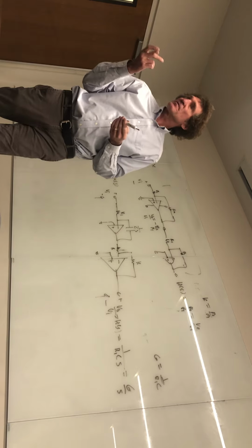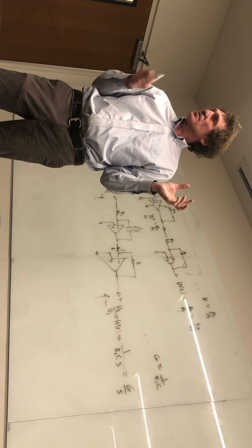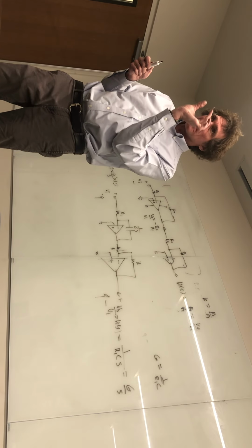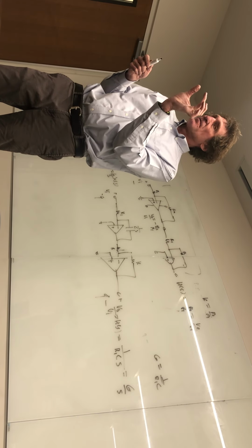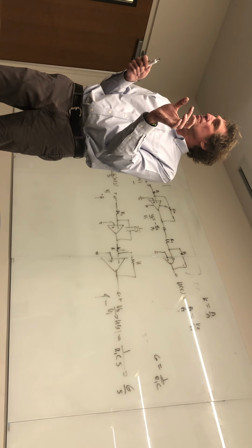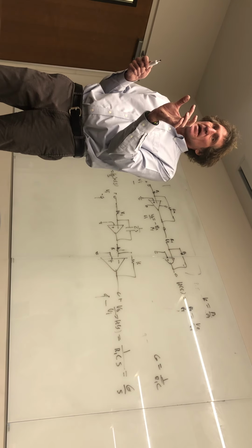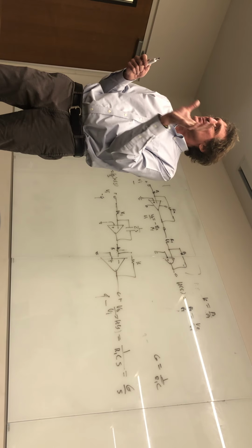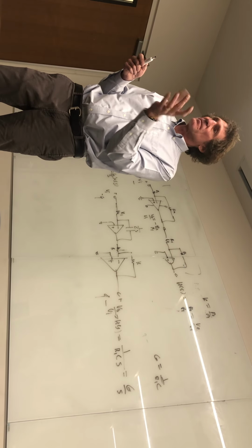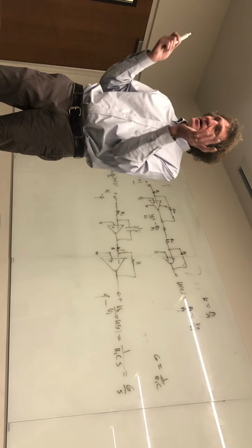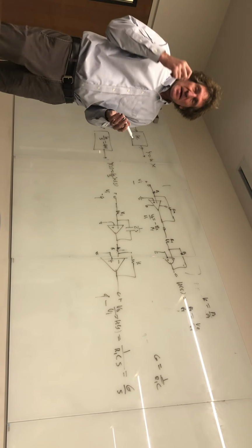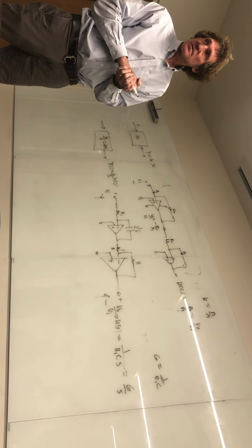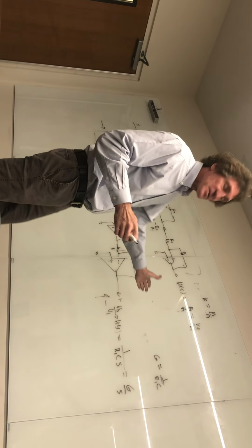So you try to make the resistances high enough so no significant current is going to flow. The little carbon barrel resistors that you guys have are usually only quarter watt. Once you're putting watts of power through them, those things will smoke. If you get RMS 1 or 2 watts, they'll burn up, and you don't want to do that. So, practically speaking, 10,000 to 100,000 ohms is what you're seeing. And this is in the preamp stage, I should say.